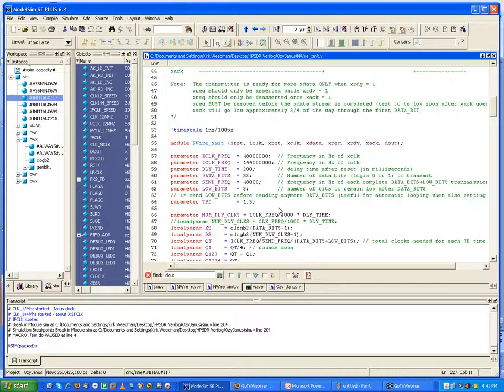Now in this design I'm assuming that the user may use 2 clock domains. So you'll notice here that I have a signal called I reset and one called I clock, and another one called X reset, another one called X clock, along with some other signals here like data, request, ready, and ack, which are all in the X. So I put an X specifying that all of these signals are in the same domain, and these ones starting with an I are in the same clock domain. This is a default value which you can override since it's a parameterized module.